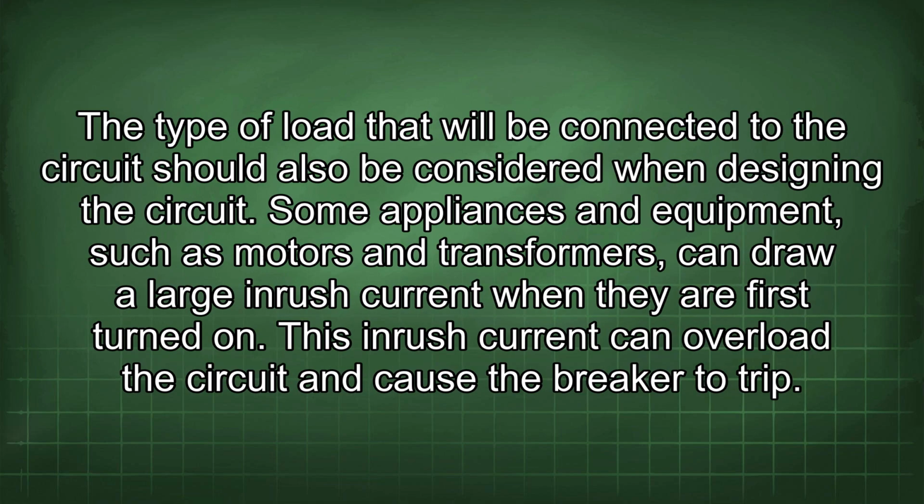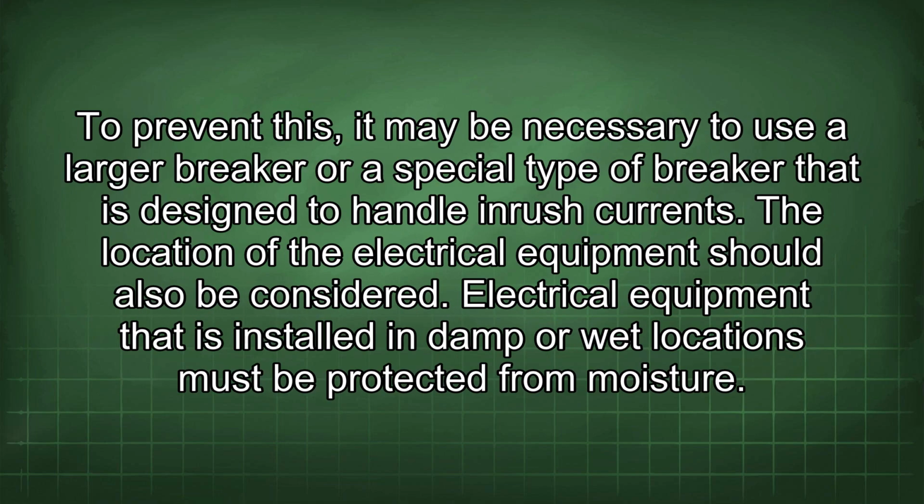The type of load that will be connected to the circuit should also be considered when designing the circuit. Some appliances and equipment, such as motors and transformers, can draw a large inrush current when they are first turned on. This inrush current can overload the circuit and cause the breaker to trip. To prevent this, it may be necessary to use a larger breaker or a special type of breaker that is designed to handle inrush currents. The location of the electrical equipment should also be considered.